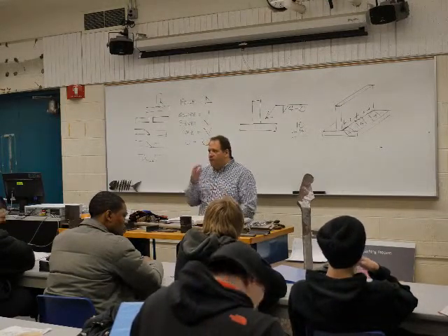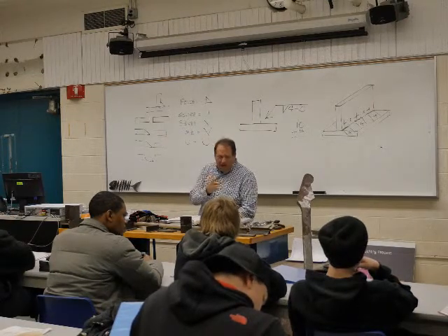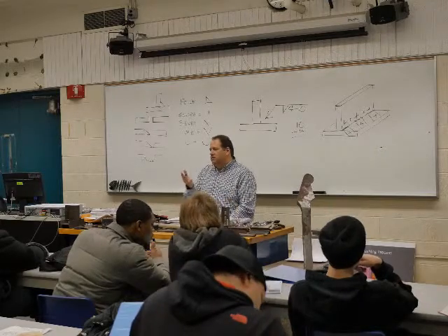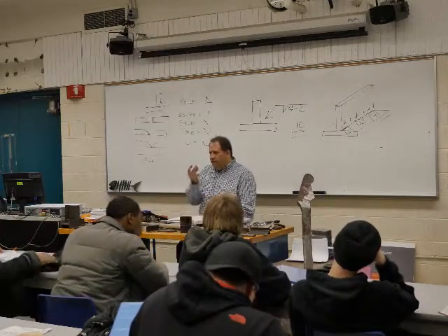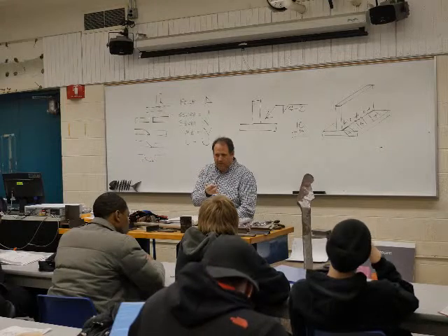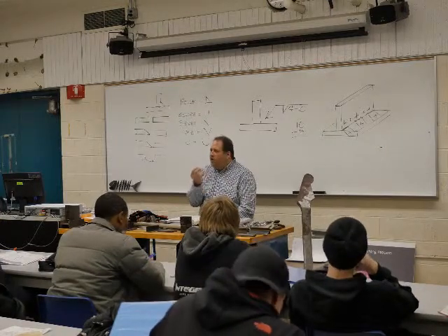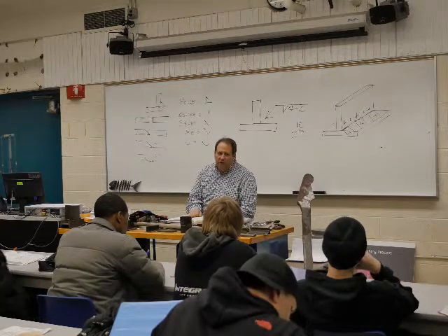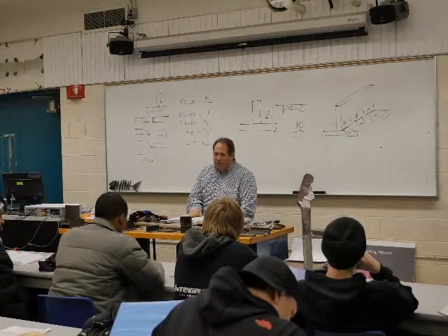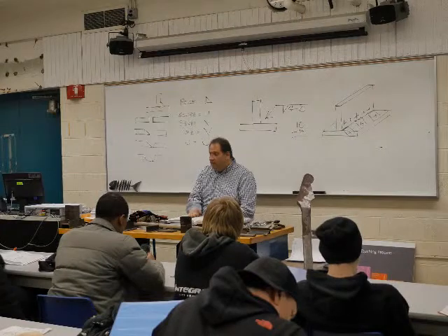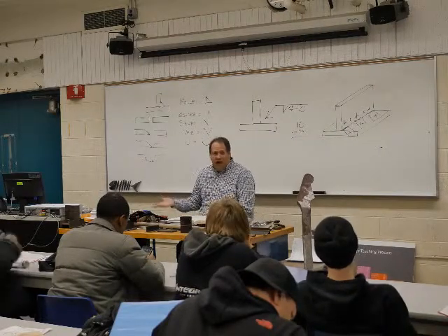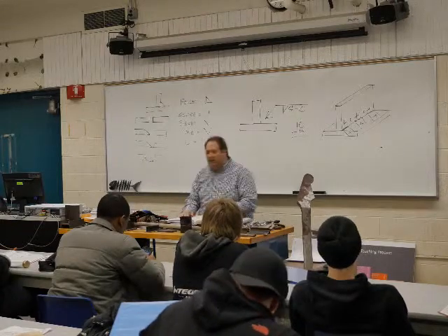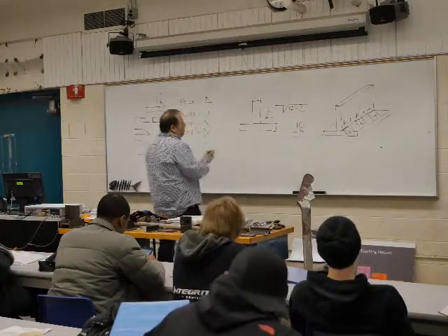We actually have 3 things that can be what's called a throat of a weld. And that is theoretical throat, effective throat, or actual throat. Now, how do you measure that? Remember how I described it with polishing it up and putting it in the etching solution? That's the only way you can measure that. It's not something you can measure with tooling that I'm using.